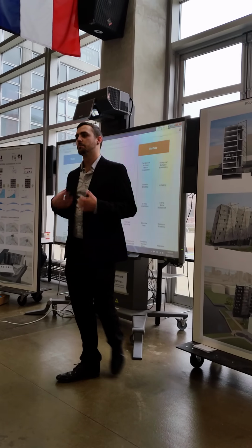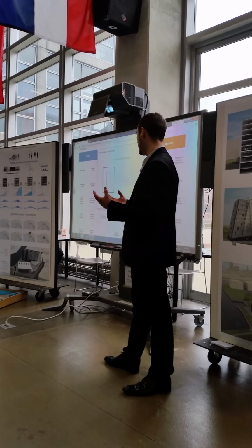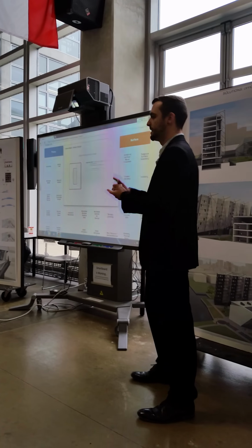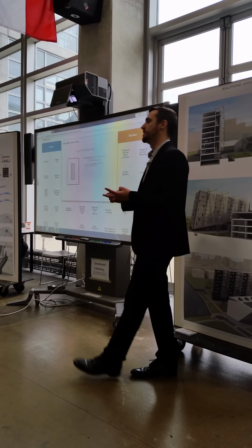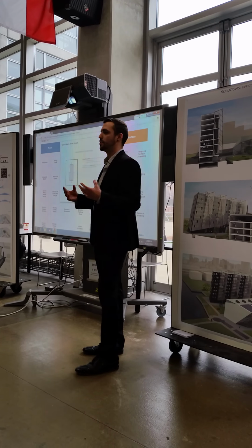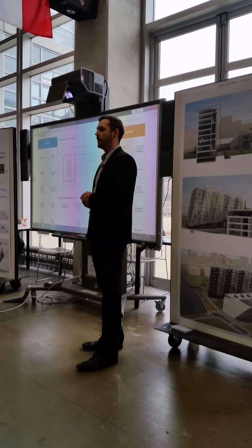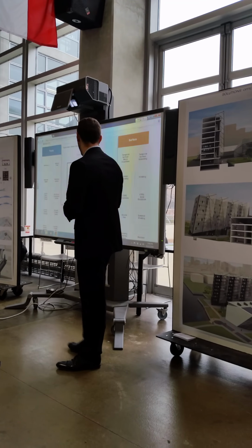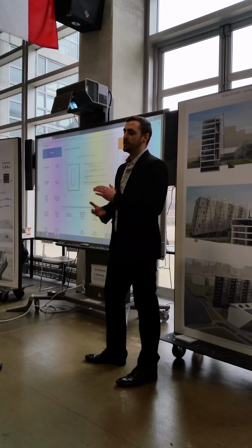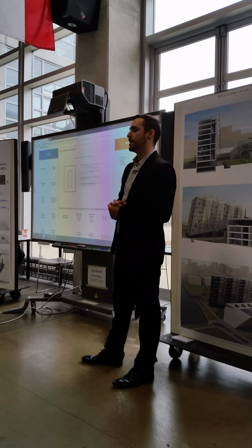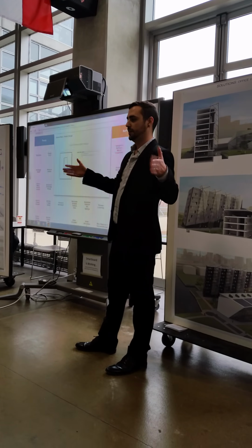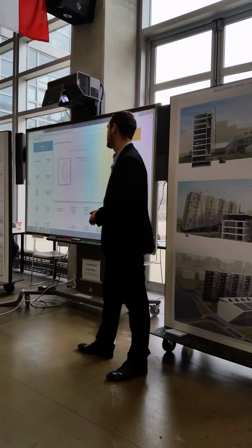Typically, in a mechanical-driven building design where you want large floor plates, you get less daylighting and less core ventilation. They're all centered around the mechanical core for optimized distribution of mechanical systems. You want to minimize the exterior surface area, control the environment inside, and kind of exclude the environment.